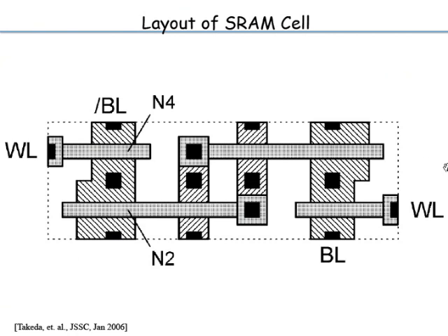Of course, you have increased the horizontal. But the horizontal is the word line, which is driven by an inverter. You can easily scale up the size of the inverter. There is only one inverter per row, whereas you don't want to increase the size of the cell. So this short, wide layout is now the standard layout structure which is used, right?